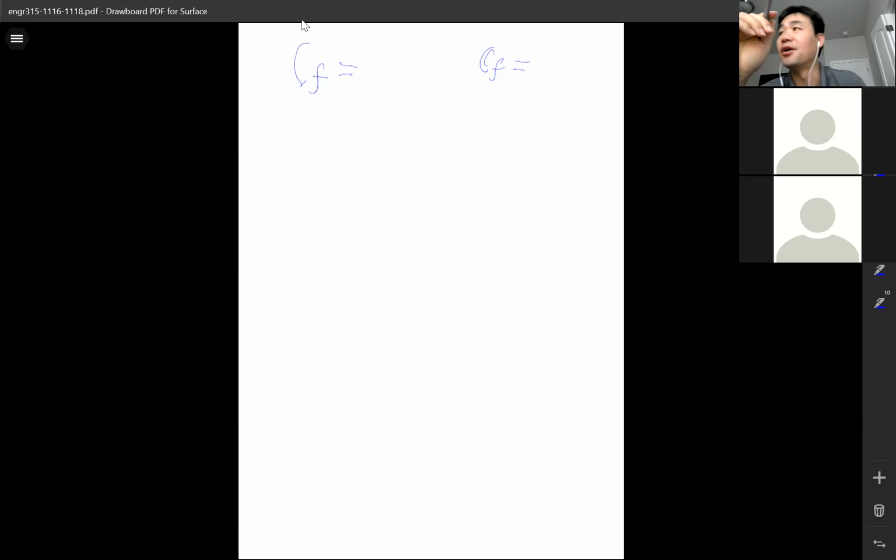It's local, so you can calculate the local shear stress. In the first class on the boundary layer, I showed you the distribution, how the shear changes along the plate direction, right? The shear actually decreases in the laminar region. Shear is calculated by CF, which is a dimensionless shear stress. Do you remember the equation for the lowercase CF? 0.664, right? Divided by what? Anybody? Divided by the square root of the local Reynolds number.